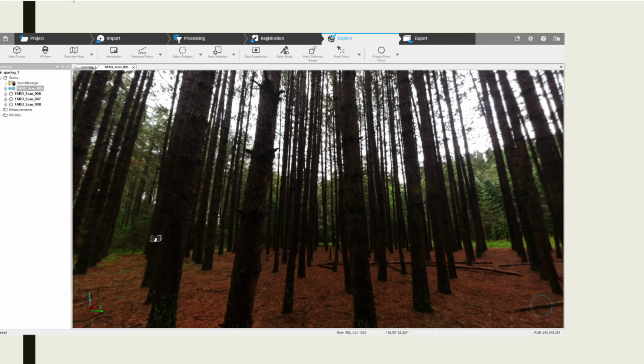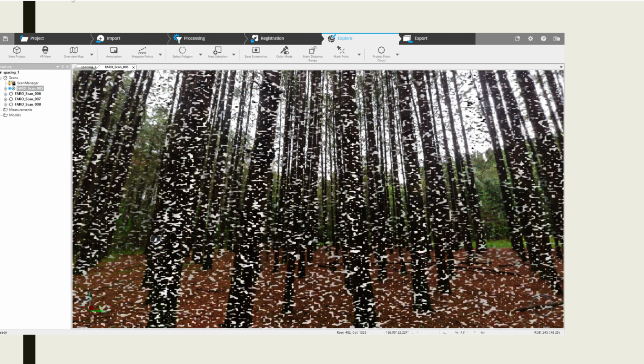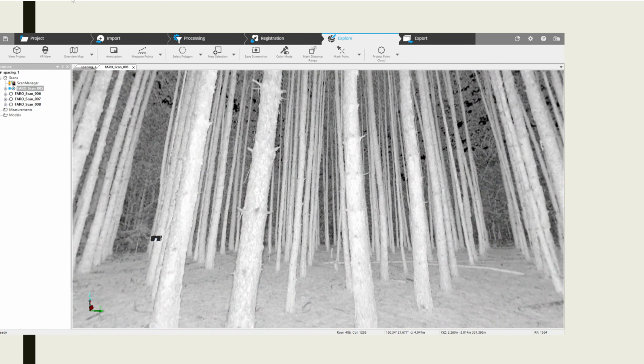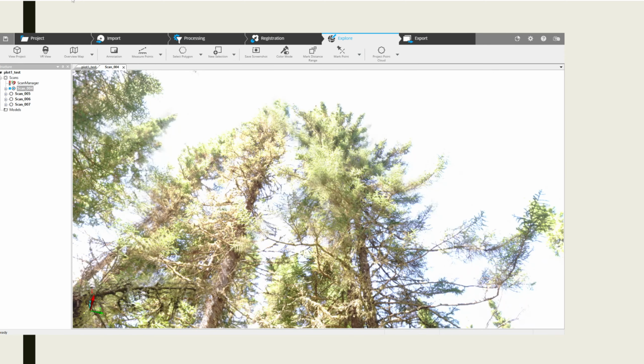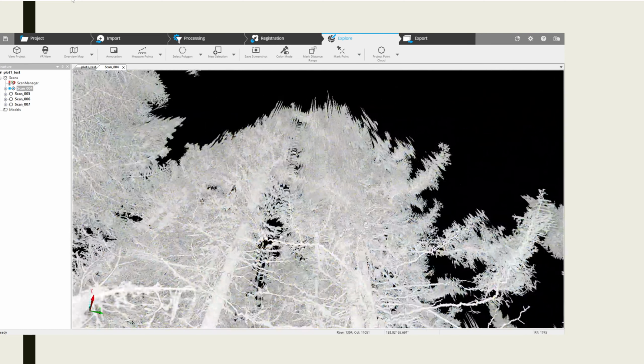The nice thing with the terrestrial LiDAR unit is that we do get colorization as an option as well. So being able to interact with the data and actually take photos and attach those together can be quite nice when it works. The problem with that approach, though, and you have to be aware of this, is that the images can sometimes hide problems. So in this case, the photo looked fine, but the point cloud was a problem. What was going on here was wind.